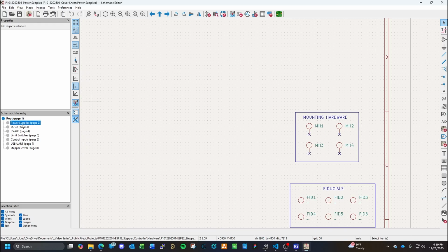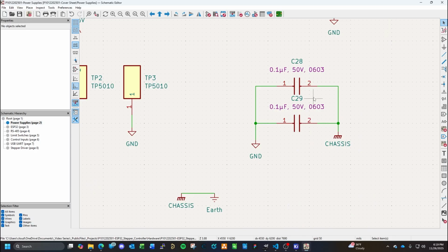What that does is it gives the voltage differential a way to jump across the capacitor. It's mainly a safety that will help jump any rapid changes in voltage, mainly on this side, to chassis ground. That's what the capacitor will do. That sudden change will automatically sync to the other side because it will technically be, for that moment, an AC voltage.